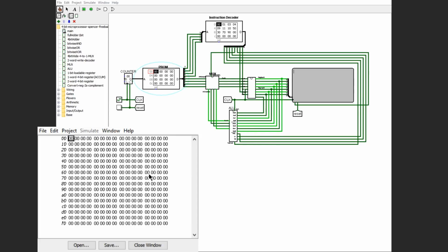So we're going to use the ALU to manipulate 3. First we'll load 3 into one of the registers, and we're going to use the exclusive OR function to flip all of the bits. So instead of it being 0, 0, 1, 1, we're going to make it 1, 1, 0, 0. So we're going to load the value F into register 0, or 1, 1, 1, 1, and then we're going to do the exclusive OR operation, which will flip the bits. We'll save that to register 0.